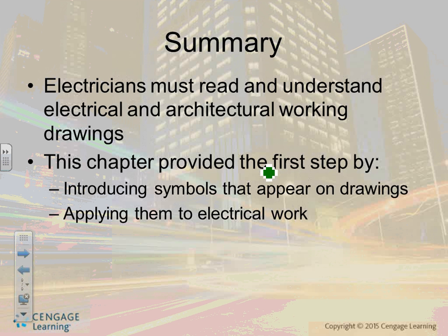You guys know what a pole is? If it's switching 2 phases, it's double pole. 3 phases, triple pole, 3 pole, single phase, single pole. A pole is a phase, typically. If they put S4 next to it, these are not 4 poles, these are 4-way switches. It always confuses people. If you put, for example, SDT, this is a single pole, double throw switch. Anybody know what single pole, double throw is? If you flip it this way, it connects to one circuit. If you flip it the other way, it connects to a different one.